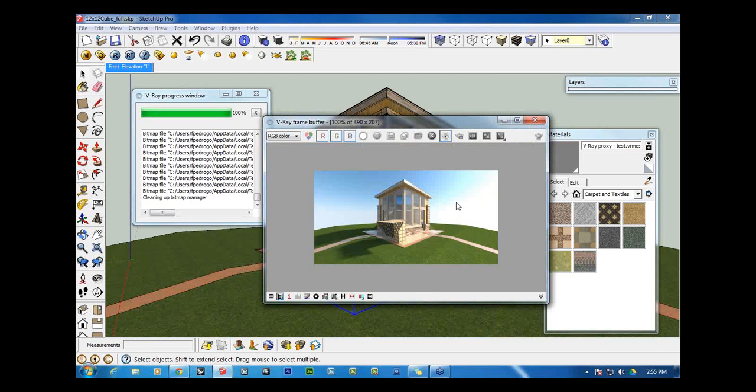because we could use proxy on proxy from 3D Max, Maya, Soft Image. So now you could get some models from 3D Max, from Maya, from Soft Image, and use those models inside SketchUp as a proxy. And you have to forget now about using low quality sofas, for example, low quality beds, because SketchUp is going to crash if you use a high polygon model. With proxy, you could use those high polygon objects, and you will be able to have a nice render.